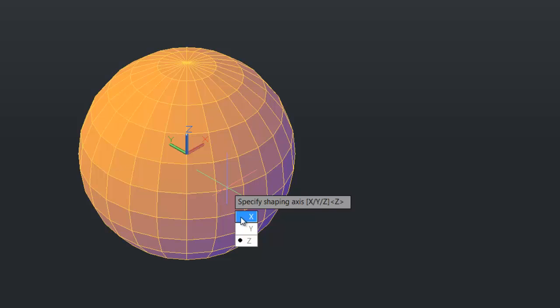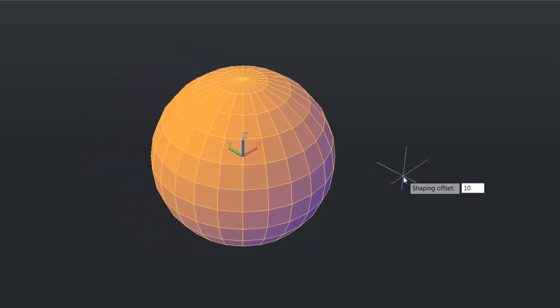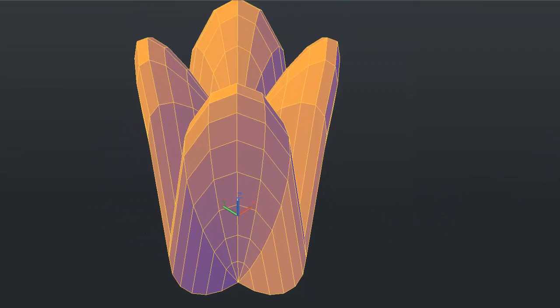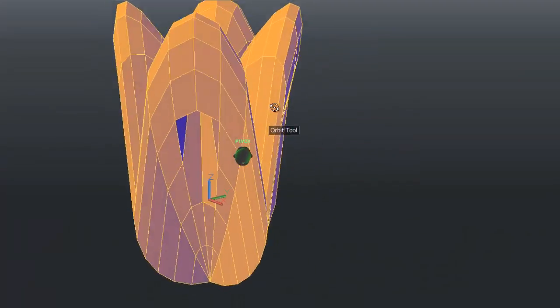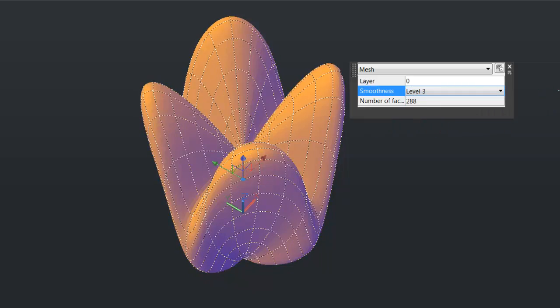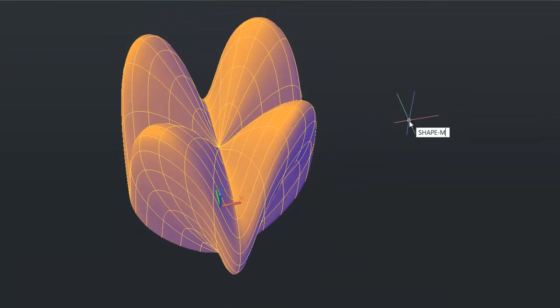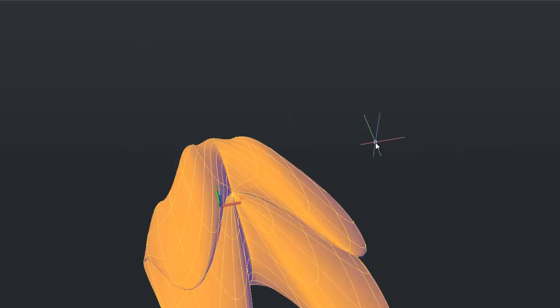We have been using flat meshes, but very interesting shapes can be obtained when the initial mesh object is one of the mesh primitives. In this case, we will explore a sphere's transformations. We apply first a transformation on the z-axis direction. You see the mesh must be smooth to close some gaps. Then a transformation on the y direction is applied to arrive to the final shape.